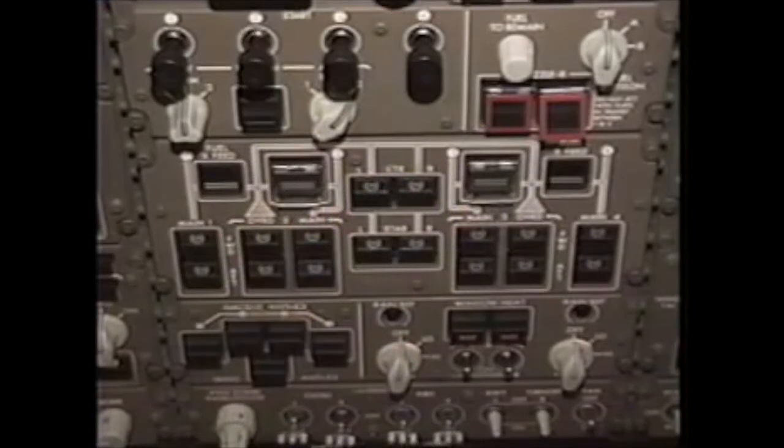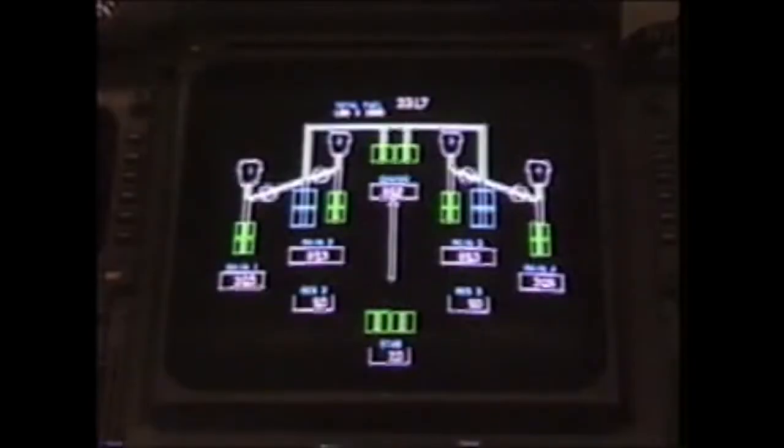The next fuel system change occurs automatically when the center wing tank volume reaches 80,000 pounds. The stabilizer pumps will automatically activate and transfer the fuel from the stabilizer to the center wing tank. This can be verified by bringing up the synoptic, noting that the center wing tank volume is 80,000 pounds. Note that the stabilizer pumps are now green, indicating the pumps are actually running, putting out pressure. Note the transfer arrow from the stabilizer tank to the center wing tank, indicating that stabilizer transfer is occurring. This will happen automatically, regardless of whether the fuel synoptic is displayed.